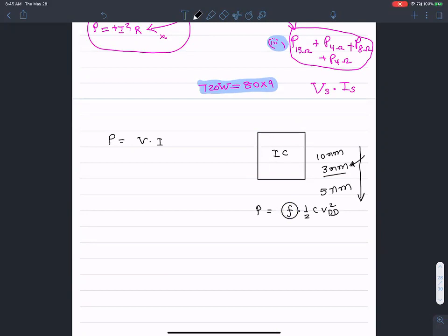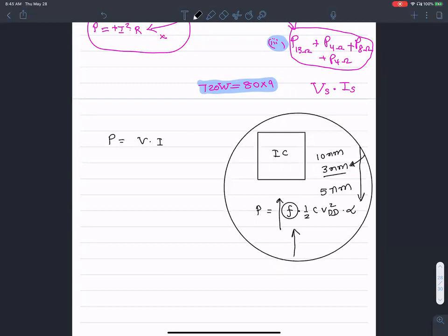If we increase alpha, the activity factor, if I'm switching capacitance on and off too fast, that's going to consume a lot of power and it generates a lot of heat. That's one of the prevailing problems that a lot of people are paying careful attention to in terms of reducing the total heat and power consumed, and dissipating the heat through proper heat sinks, good design, and so on.